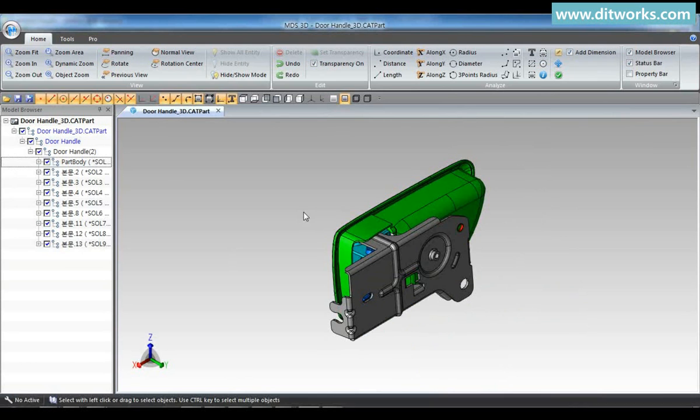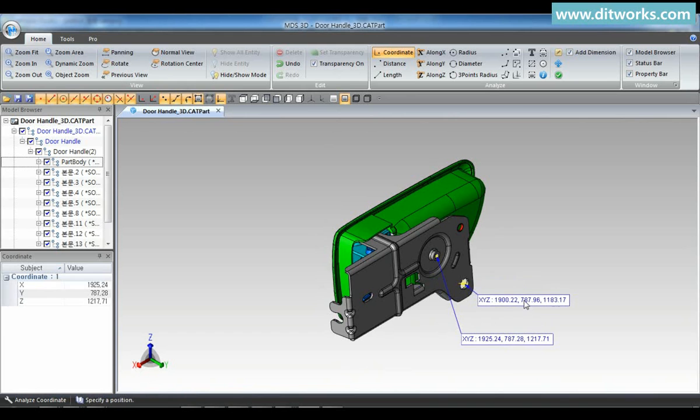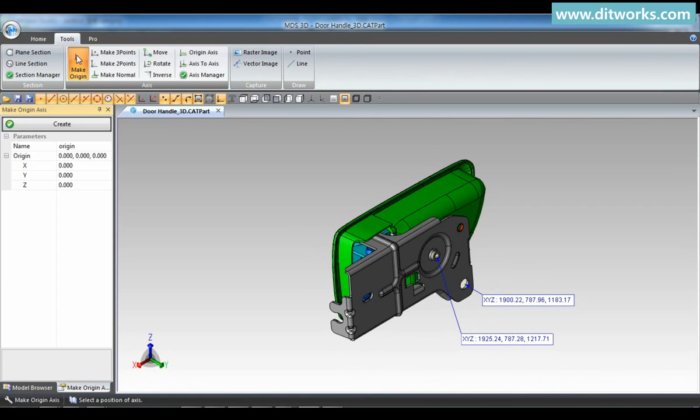Next, the menu to introduce this time is the dimension. 3D dimensions can be used to check the X, Y, Z coordinates of the origin reference. You can select the exact location easily, because it automatically recognizes the feature points of the shape. It can also be used as a reference coordinate function to check the X, Y, Z coordinate values around a randomly generated axis. Now, check the reference coordinate to create an arbitrary axis.